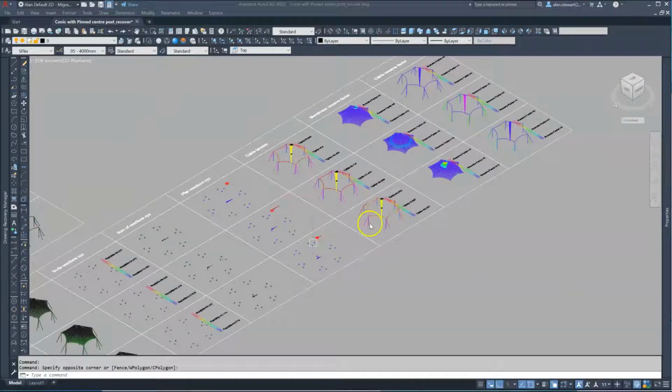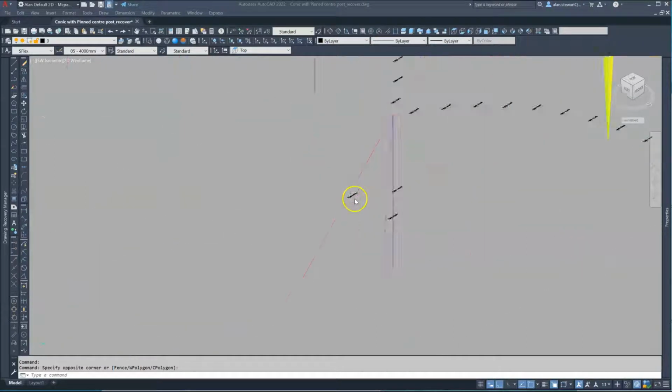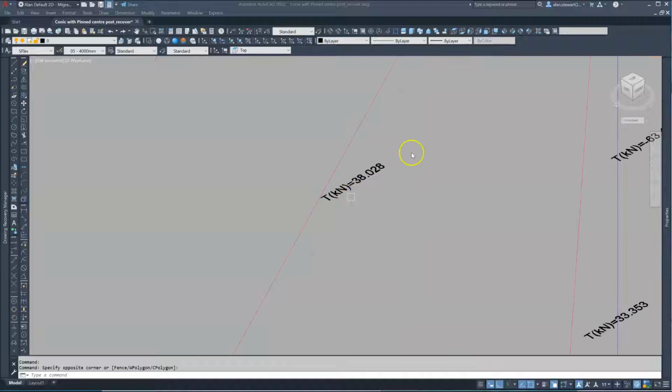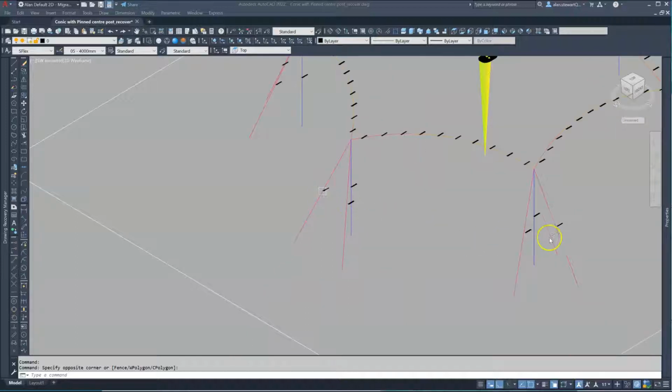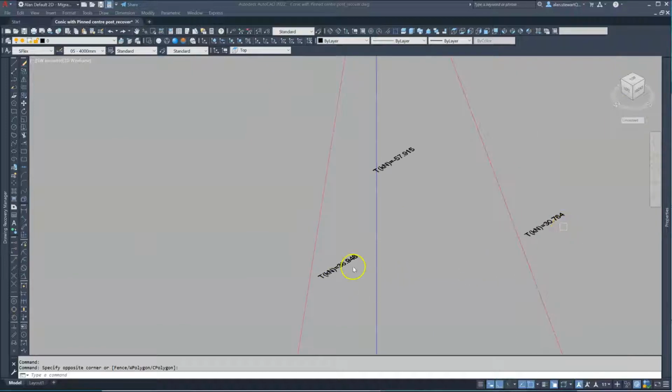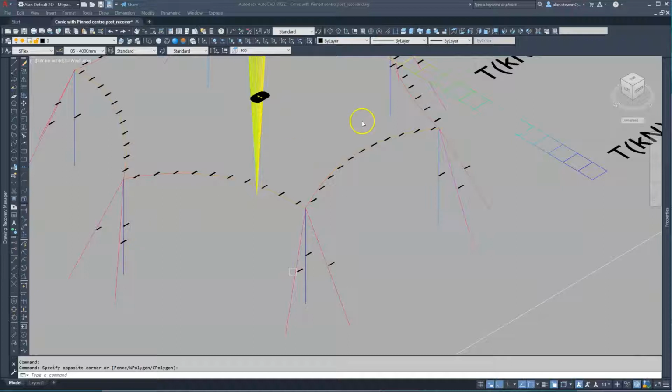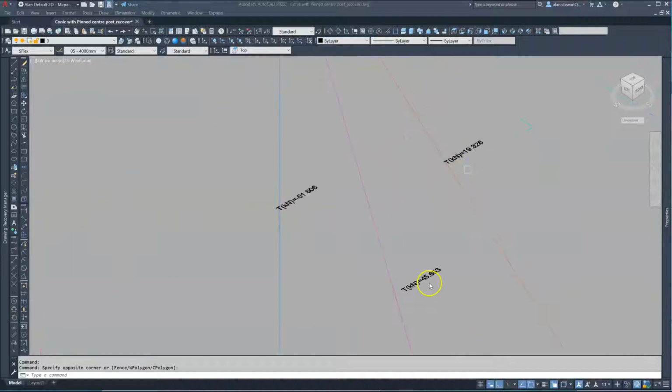We can also see, looking at the cable tensions, that we've got asymmetry now in the backstay cables. So 33 here, here 36 and 30, so the structure's being pushed sideways, and here we can see 45 and 19.